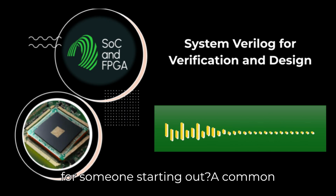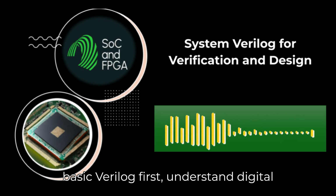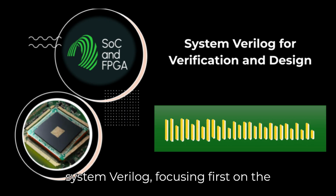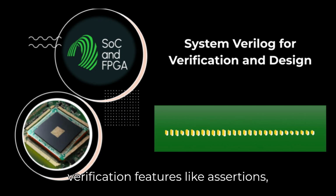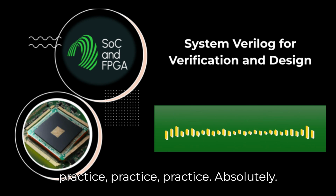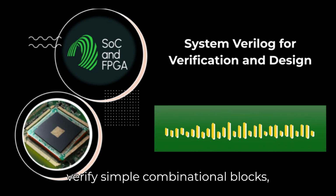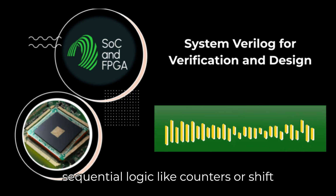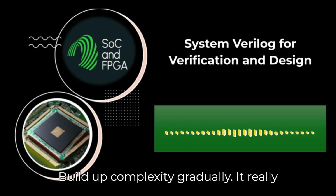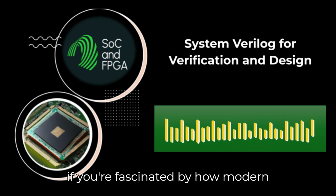Any practical advice for someone starting out? A common recommendation is to get a solid grasp of basic Verilog first, understand digital design concepts, then transition to SystemVerilog, focusing first on the design enhancements, then diving into the verification features like assertions, coverage, and maybe eventually UVM. And practice, practice, practice. Absolutely. Start with small projects. Design and verify simple combinational blocks, sequential logic like counters or shift registers, maybe a small FIFO or an ALU. Build up complexity gradually. It really is a deep field, but incredibly rewarding if you're fascinated by how modern technology actually works.